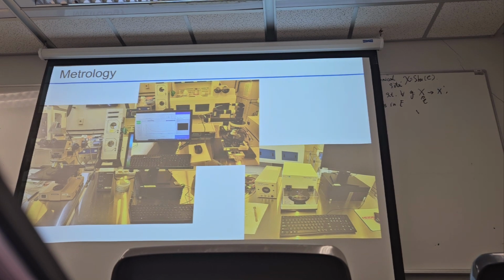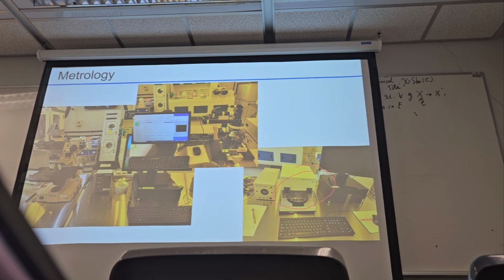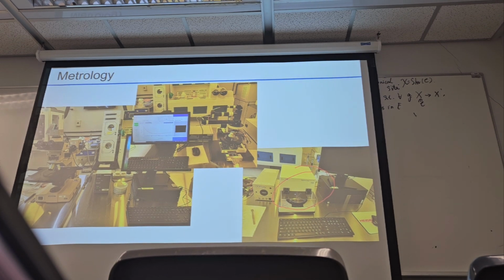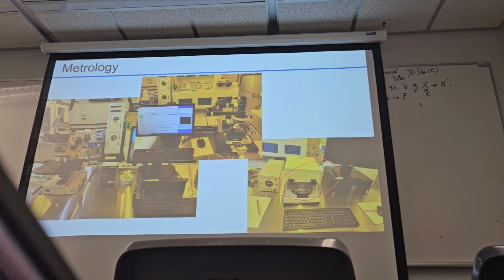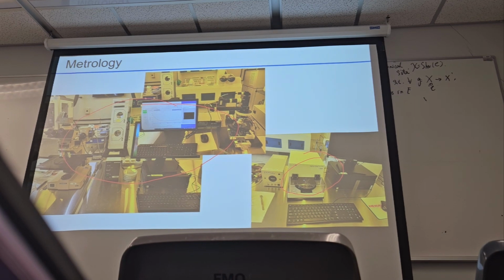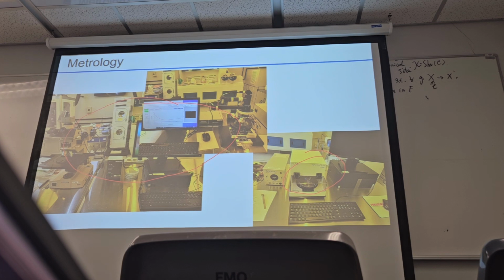Interferometry, right? It can help us to measure the thickness. And we also tried the profile step meter, which is shown here, right? So after the etching, when you have the step, you can use the profile step meter to help you to see the thickness of the step, which is more accurate compared to the first 2 optical methods. Right? You need to understand the difference among these 3 methods, right?